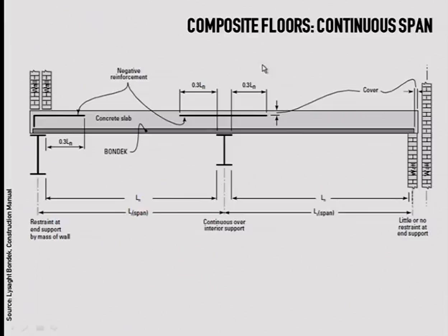And what happens in this case, when you have a beam in the middle, so that the span is not free, you change the system. So in this case, you have a diagram of moment that becomes negative here, then there is another peak here, and then it becomes positive again and negative.